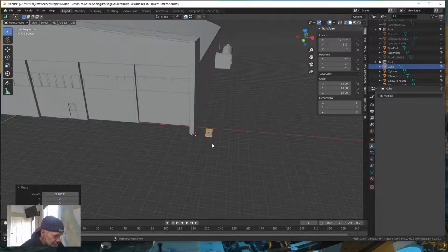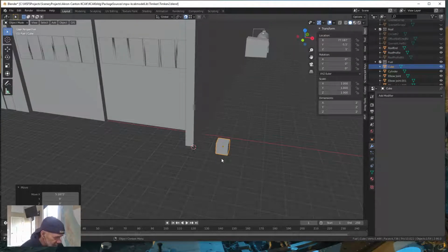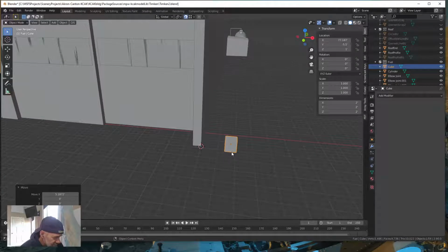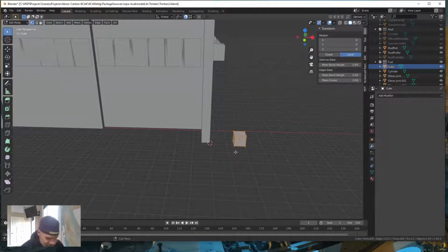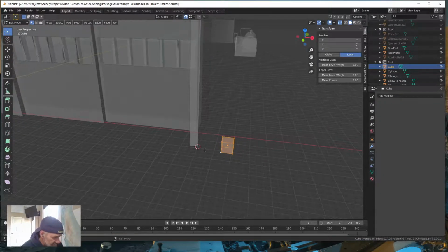All right, so if I go into edit mode and I select, okay, go ghost mode, I have all my vertices selected. Select this corner once, twice to make it active, and let's snap that right to that corner.